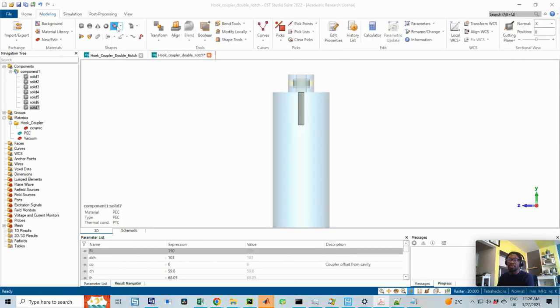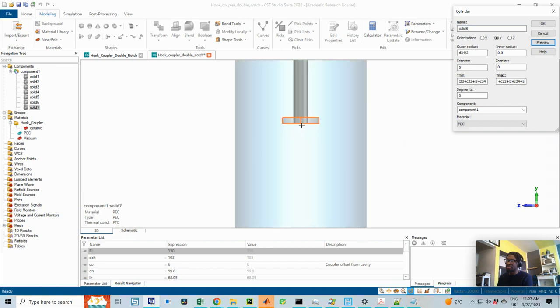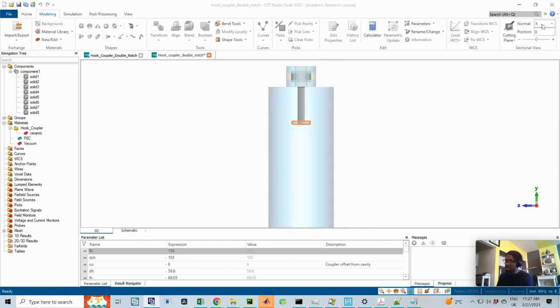I'm going to go to this and then escape, and orientation y, then the radius is d34 divided by 2. I think I have to update the copy. The y minimum is y4, then the y max would be plus 5. I just used 5 millimeters so I could preview. Okay, without the L4, so preview. Yes, so that's what I have, and I click on OK.